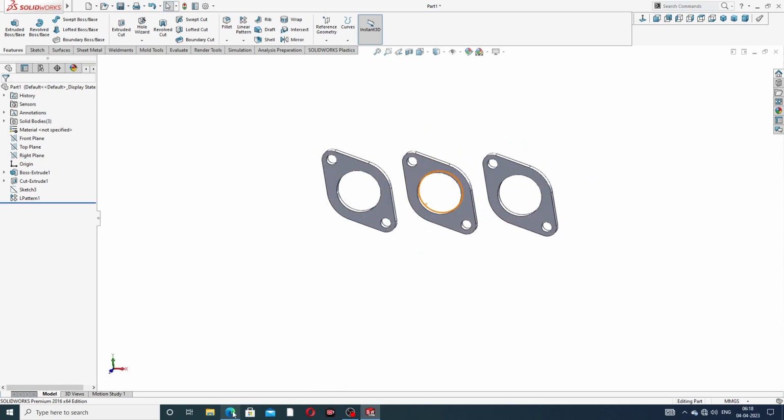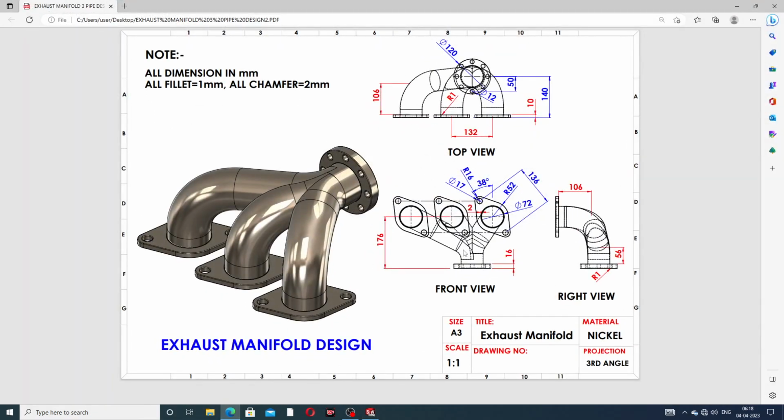Okay, all is perfect, the 3 patterns are correct. Next point is drawing this body, and this body is 176 millimeter. Use the top plane, and use this body. This big circle is 120 millimeter, and this point to this distance is 50 millimeter, correct, and this point to this distance is 140 millimeter, perfect. Okay, all is correct, and this small circle is 12 millimeter.